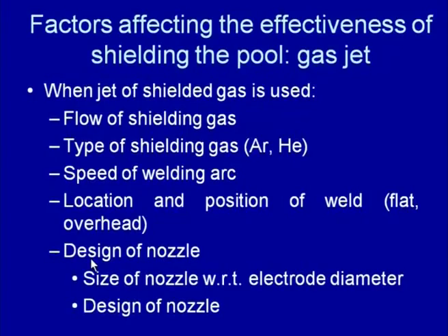Another factor associated with the shielding is the design of the nozzle being used to provide a jet of the gases, which will form a cover all around the arc region to protect it from atmospheric contamination.